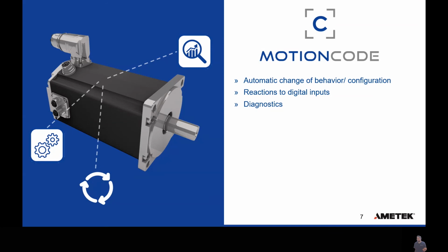Another point is diagnostics. For example, the motion is still controlled by a PLC. The commands come from there, but I want to have some additional diagnostics on the motor. For example, supervision of temperature, of currents, and just have an idea what's going on, some cycle counters that can be programmed directly on the motor, downloaded there, and so place this on every motor, and it delivers the information you want.